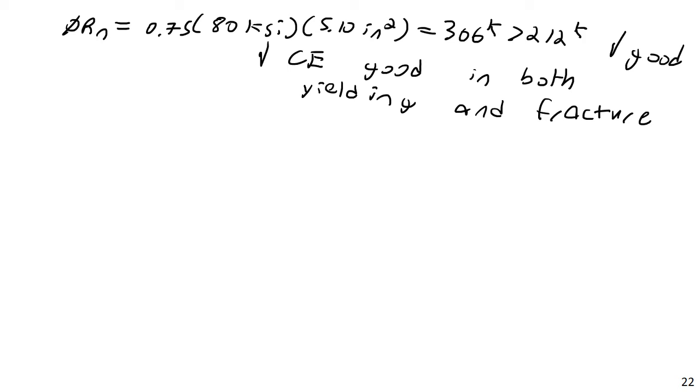However, if you have something that's almost across the line, say it needs to carry 900 kips, and according to your current code check your design capacity is only 895, well, maybe going to that bolt stagger could help, if the failure mode you're dealing with is a fracture failure mode, not yielding, that's not going to help you. But if you have a fracture failure mode controlling, that might actually be a case where that would make a difference.